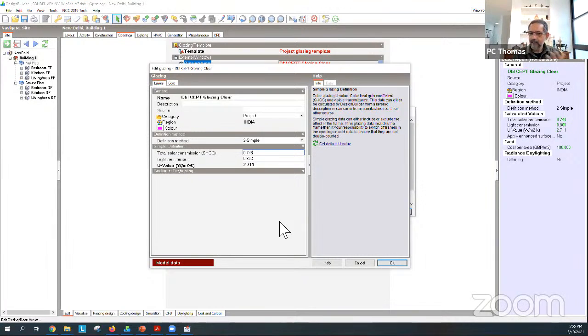Okay. If you're in many parts of India and the temperatures are sort of 20, 25 most of the time, and you want to keep it around there, well then, the heat transfer through this component may not be that important. It may be much more important for you to shade it or to look at the solar heat gain